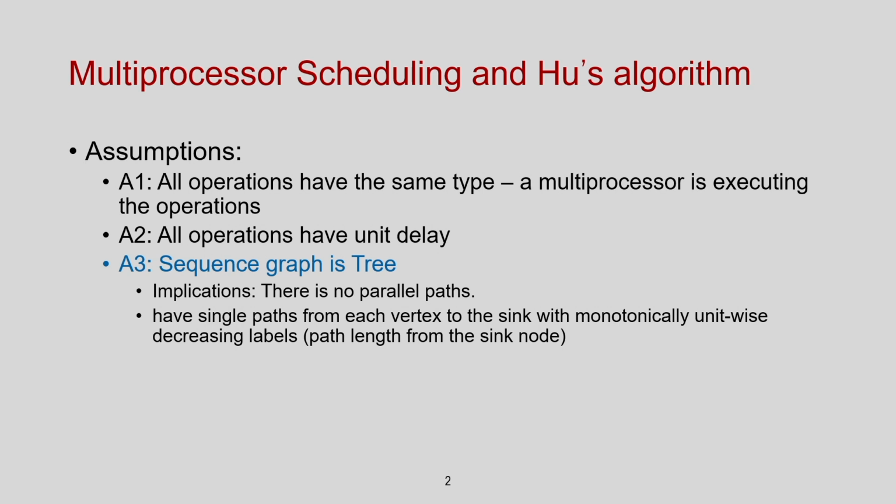If you have n operations available in a time step and you have to select k, you can select the subset based on those nodes' distance from the sink node, and that guarantees the solution will result in the minimum latency to schedule those operations. This is what we learned in the previous class, with the Hu's algorithm that does exactly this.